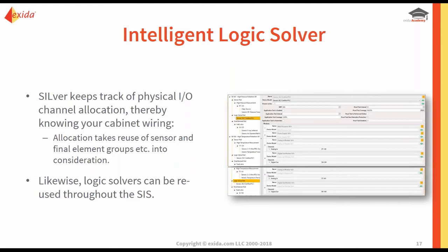There's a module for the main processor, the power supply, and then you have your input-output modules. And you can see the sensors and final elements that are attributed to those modules, which is very cool. And so it's an intelligent logic solver design. This is totally new from version 3 and definitely more accurate. So that is one cool thing to add.